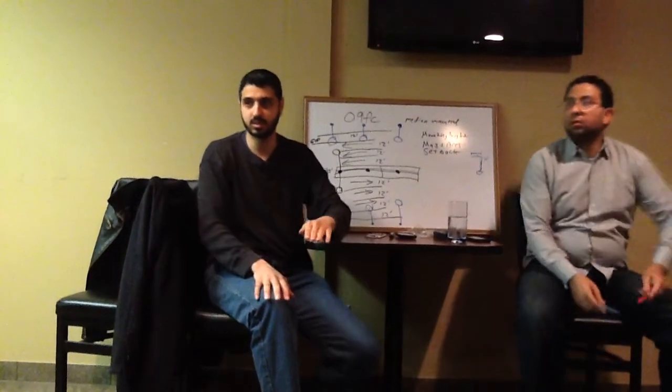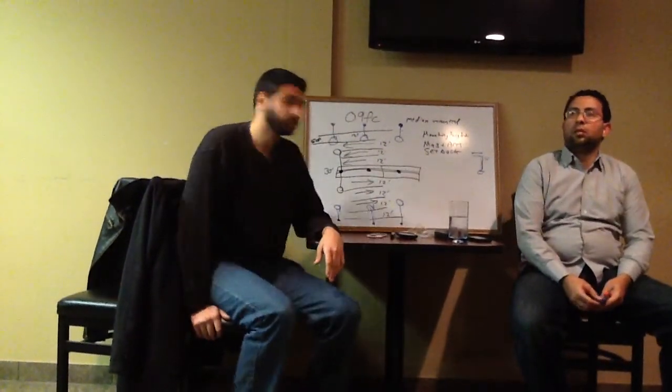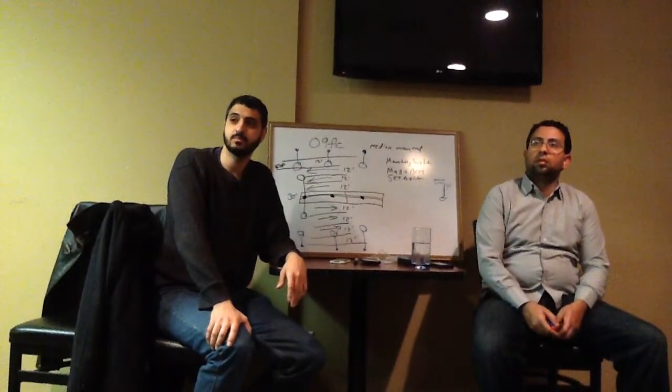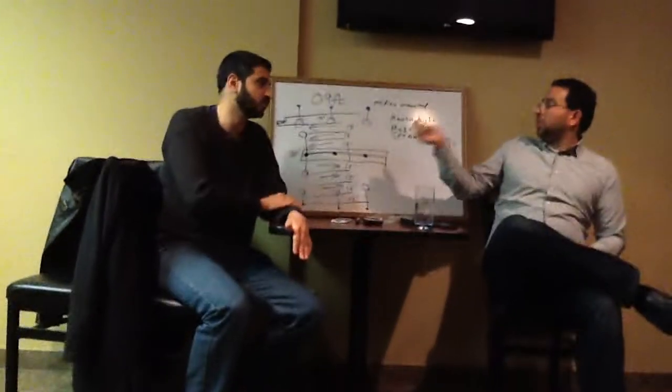One of the points, when you mentioned it, is mount height versus pole height. In most cases, if you look at the arm, it's arced. So here's the pole, and the arm is arced like this. So there's actually an additional height. It's not just the top of the pole, it's adding maybe a foot or whatever to it. That's where this becomes important. You have to consider the whole height of the pole plus the arm, all the way to the ground.